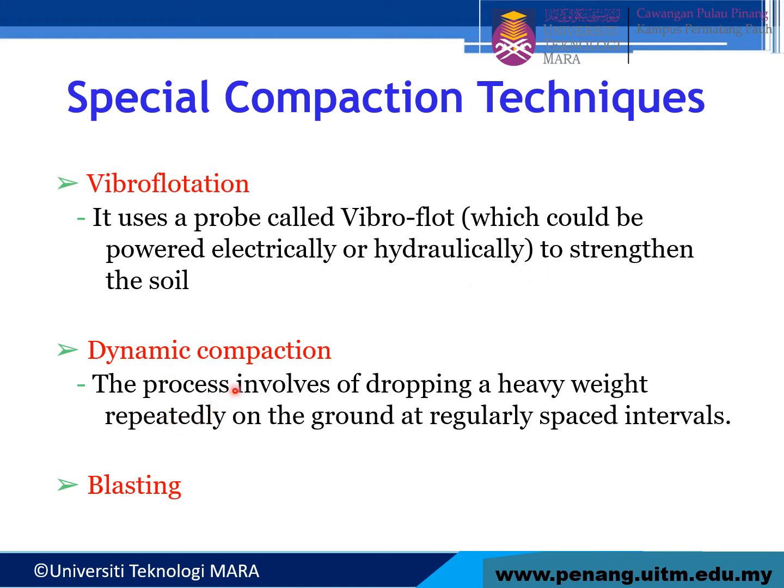Dynamic compaction is a process involving dropping a heavy weight repeatedly on the ground at regularly spaced intervals. So that means we have different intervals, different places. Then we drop the heavy weight from a certain design height. And then another compaction technique is blasting.